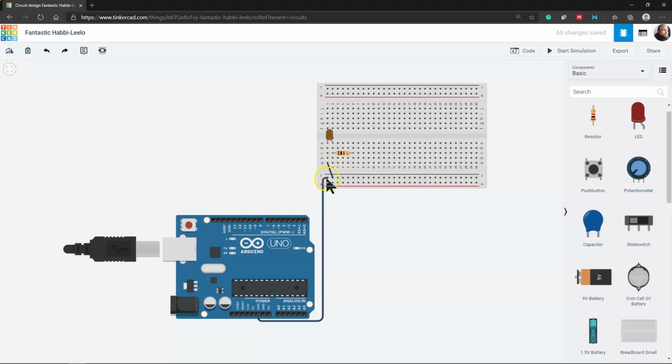And we can leave the ground because we still want to have that circuit, because this is going to provide the power, so that's going to become your kind of power source for the one circuit we're hooking up. But otherwise, we'd still want the actual ground hooked up, because this is the ground that's coming back to the Arduino to complete that actual circuit. So instead, we want to hook here where we had power before over to whatever pin we choose. So arbitrarily, for no real reason, I am going to choose the pin 8 and bring this over.